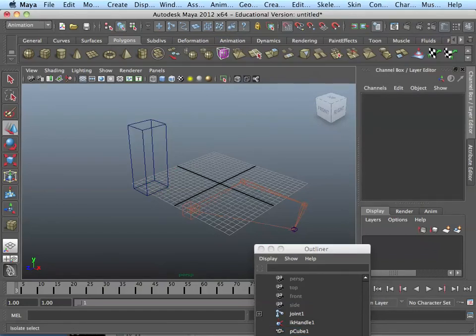So now we start to talk about real life, right? Let's say you were going to build this arm out of servos. Well, you can test in the real world: what is my range of motion? How many actual degrees do I get if I tell it 0 and if I tell it 180? Like, how many physical degrees do I get? And one thing I forgot to tell you last time, a way to do that, but I'll give you the key to the world.